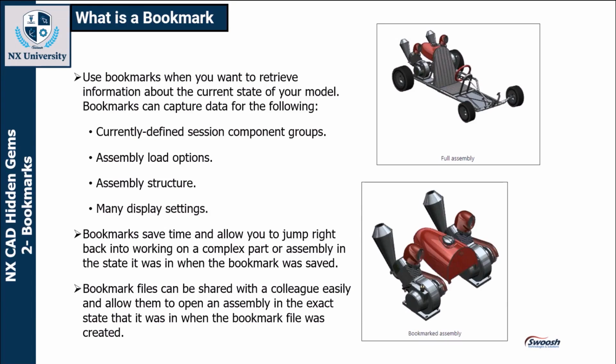We can use these bookmarks when we want to retrieve information about current states of our model, and bookmarks can capture data for the following items: currently defined session component groups, assembly load options, assembly structure, as well as many different display settings inside that environment. So these bookmarks can save time and allow you to jump right back into work on your complex parts or assembly in the state that it was in when the bookmark was actually saved. A bookmark file can be shared with your colleagues, and we can allow them to open an assembly in the exact state that it was in when that bookmark file was created.